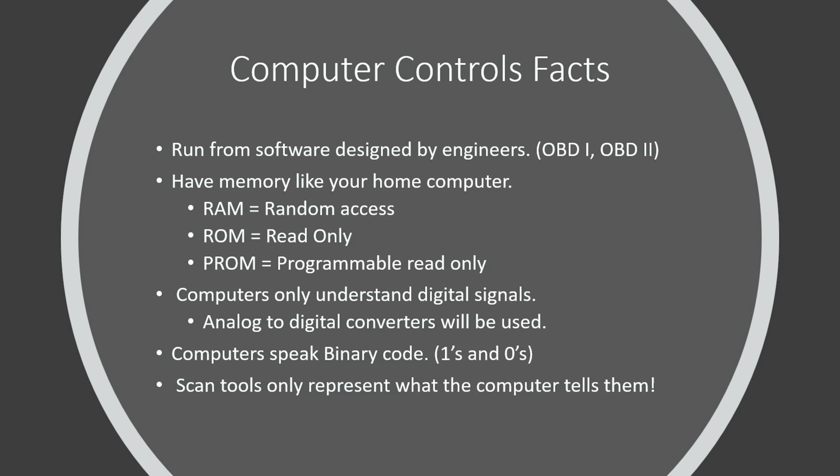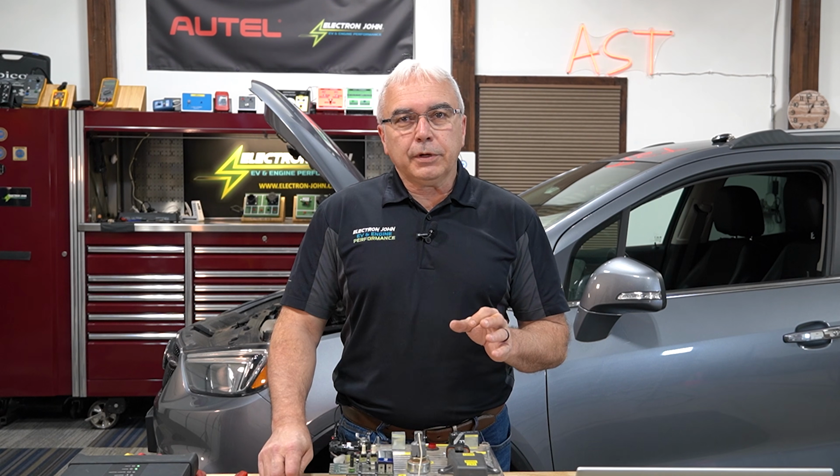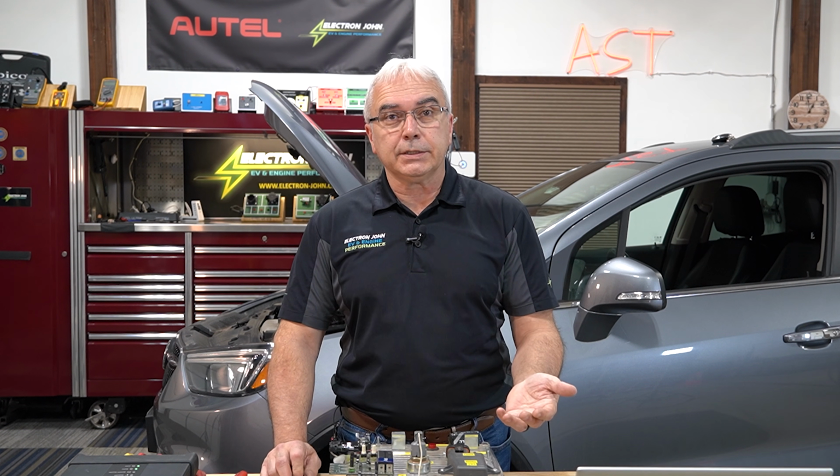So binary coding, zeros and ones, something's on or it's off, right? They cannot understand any type of analytical input, which you know there's a ton of analytical sensors on a vehicle. Stuff along the lines of a throttle position or pedal position sensor, temperature sensors, whatever. So this is something important for us to understand, because that means that all of those signals, if they're being created, somewhere there has to be an analog to digital converter to convert that to something that a car's computer can understand.